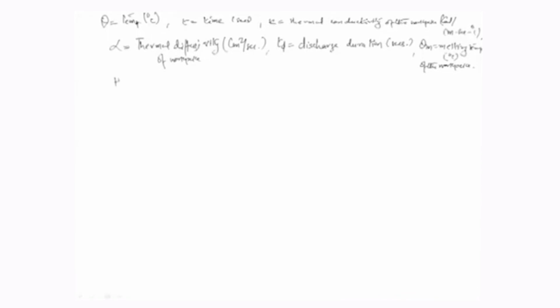We also assume H to be the input heat rate in calories. So input heat which comes to that small area where the spark contacts, let this heat be in calories, unit of energy. And the job now is simple, because we really need to estimate what the equation for heat conduction for the cylindrical geometry is.